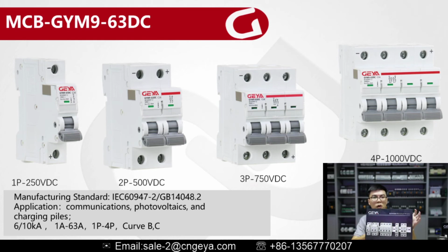The single pole of this GYM9 DC breaker has a rated voltage of 250 volts, and the double pole is 500 volts, and the triple pole is 750 DC volts, and the 4 pole can reach 1000 volts.